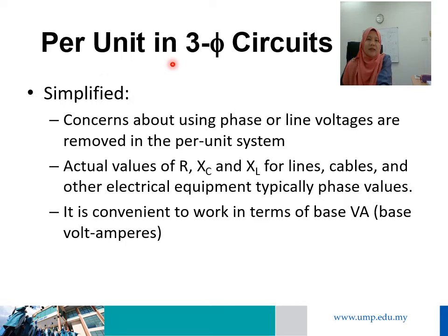In the per unit system in a three-phase circuit, we are concerned about using phase or line voltage, and this can be removed in the per unit system. The actual values of the resistance, the reactance due to capacitance, and the reactance due to inductance for the lines, cables, and other electrical equipment are typically in phase values. It is convenient to work in terms of the base VA or the base volt-amperes.